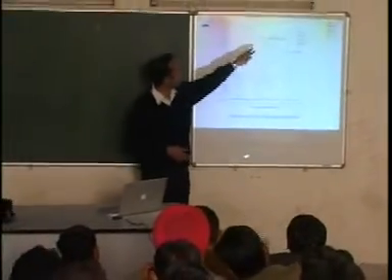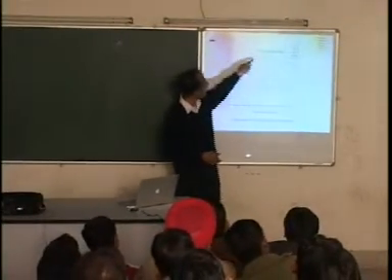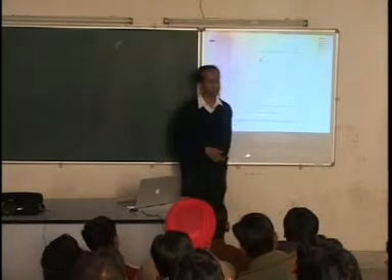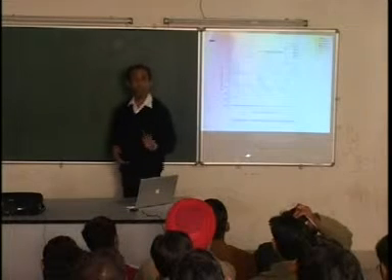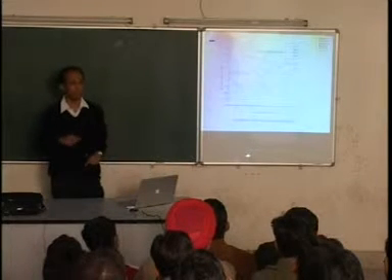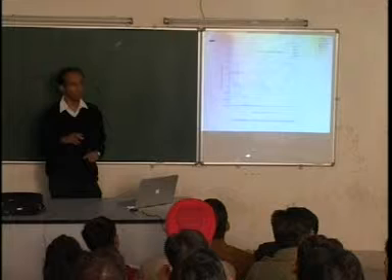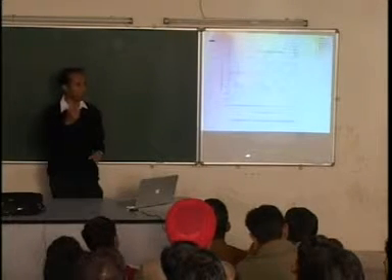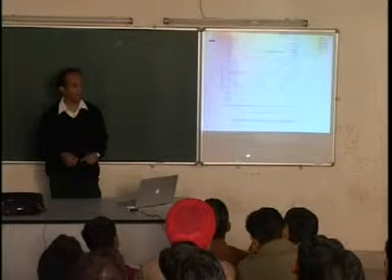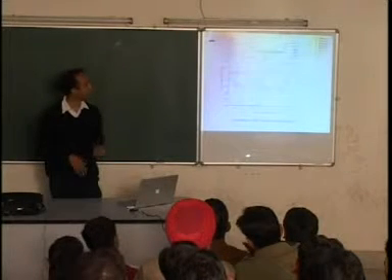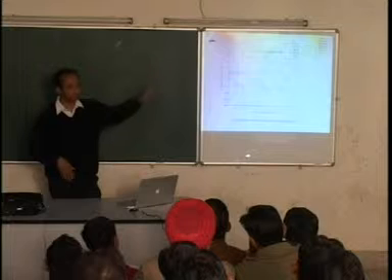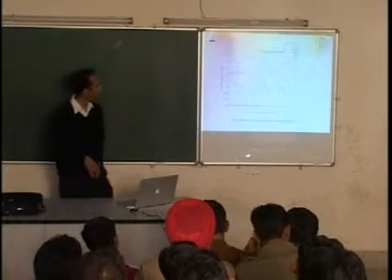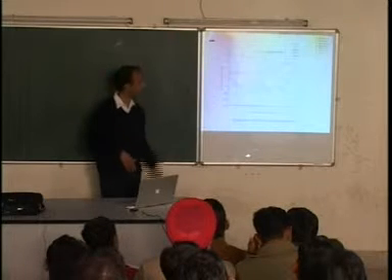So this is what it looks like. Basically the whole point of all this is that it gives you about 7 dB gain at this frequency. Which means the rest of the active antenna, the line losses, that 50% means 3 dB loss in that antenna, all that combined should not exceed 7 dB. In fact, it should not be more than 5 dB or so. That's all this tells me. This is measured, by the way.